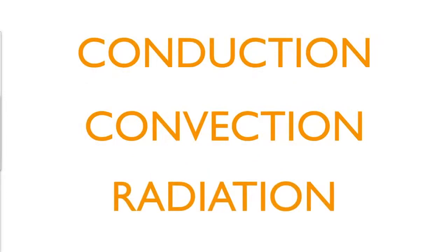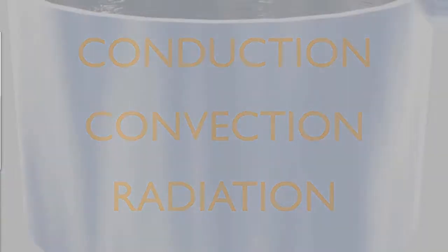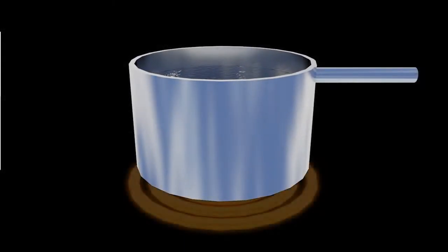So to begin, let's review the basic factors relating to heat, air and moisture movement, starting with heat transfer. In terms of energy performance, managing heat transfer is the most obvious consideration in our design process. There are three basic modes of heat transfer that are present in all buildings to some extent: conduction, convection and radiation. The simplest way to illustrate all three is heating a pan of water on a hob.